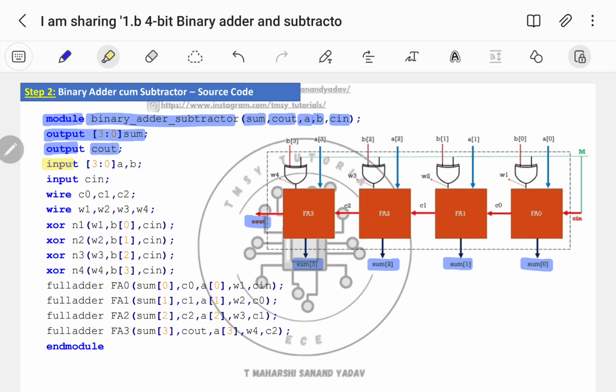Next, coming to inputs. Inputs 3 down to 0, A comma B. So 3 down to 0 means A of 3, A of 2, A of 1, A of 0. Similarly, B of 3, B of 2, B of 1, B of 0. Next, input Cin. Let me check how many wires are there. So C0, C1, C2 are the wires. Anything which is present within this dotted box is called a module. And these lines are not having any name, so I am calling them wires.